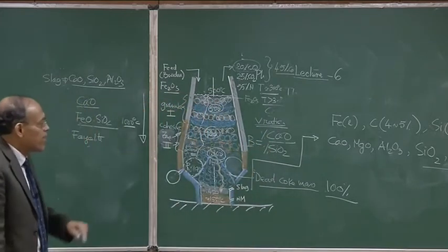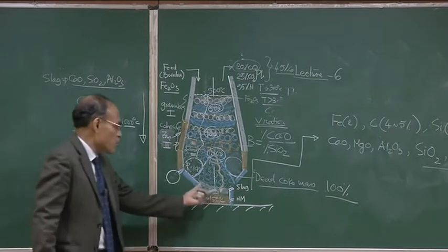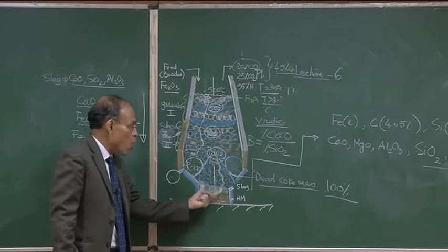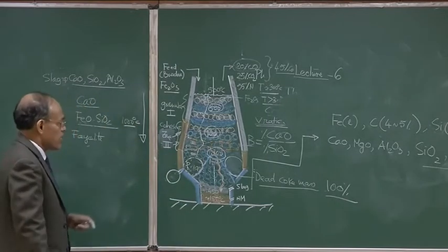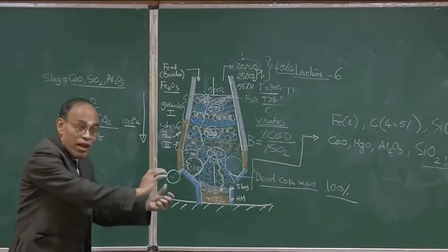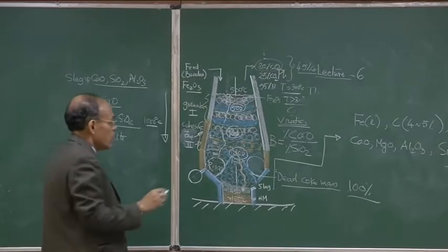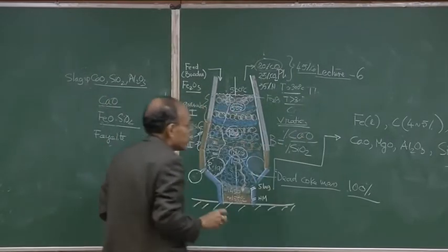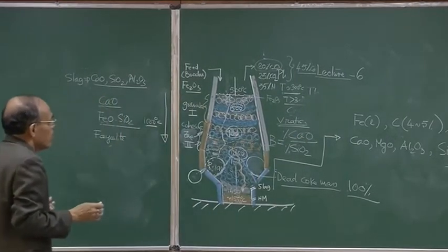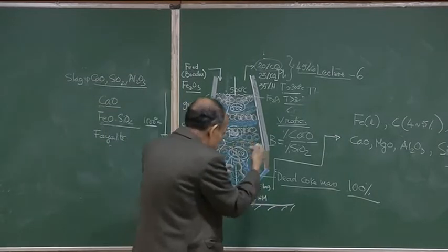So, this changes dynamically. Now, we must understand that if the slag volume is more, or if we require a higher basicity for some reason, we will see what that reason is. In that case, we may have to operate at a very high temperature, because CaO does not soften, or it dissolves in calcium silicate.